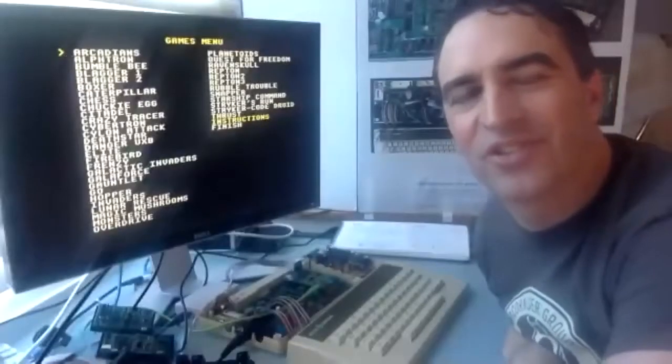There's the minor issue that the Z80 coprocessor injects Beeb-specific code back into the host, so you actually have to patch the coprocessor to get it to work on the Electron. It uploads 6502 code that pokes back to the tube register, so if the tube register has moved, it doesn't work.